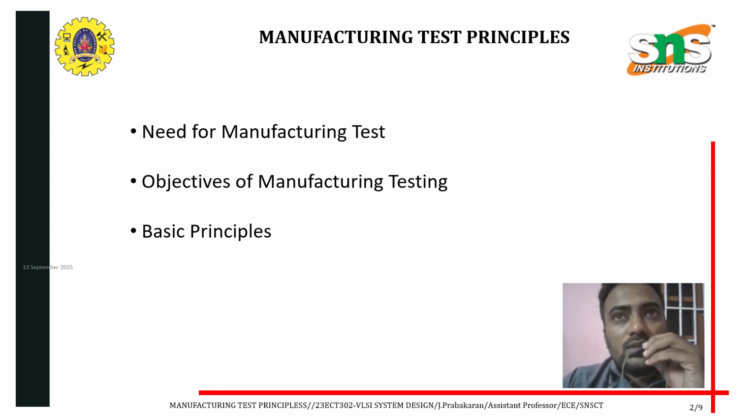And already we have discussed one of the principles, design for testability, DFT, which introduces special design features to make testing easier, ensuring faults are detectable at the output. What are the DFT techniques? Scan-based test, built-in self-test, boundary scan test. All of these come under DFT.